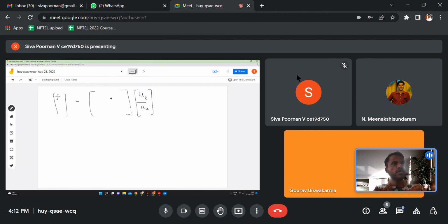So once we are able to split them into knowns and unknowns, then whatever stiffness matrix arises after that splitting, we are going to name it k11, k12, k21 and k22. You're right, it is k11, k12. This is bigger, it's not just a number. Okay, it is a submatrix itself. K12, k21 and k22. Okay, I'm also going to name the forces f1 and f2, and the displacements u1 and u2.